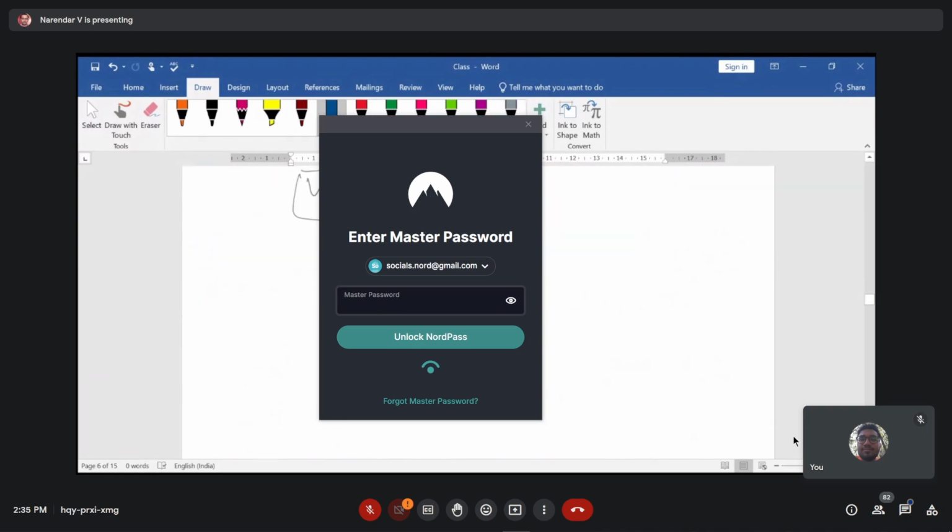Let me redraw it again. The resistor is referred to as RD, the transistor that we are applying here, and then this is the point where we are tapping, called Vout. This is VDD, right? And then there is a current in the device called ID, and this is your VDS, and VDS is equivalent to Vout. And this is your VGS. When your small signal is 0, then VGS is equal to VGG.